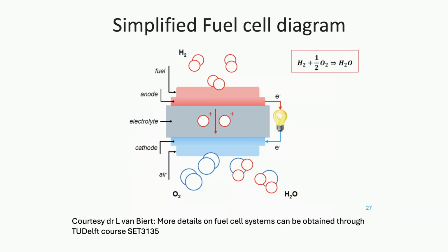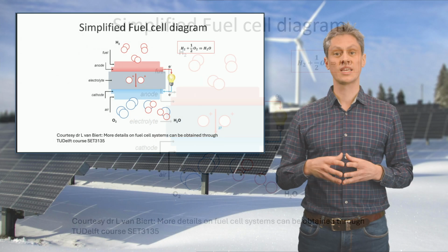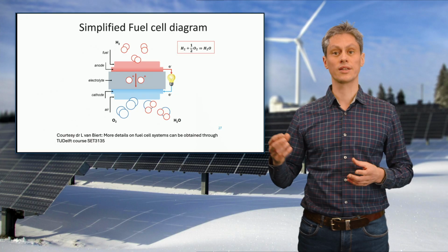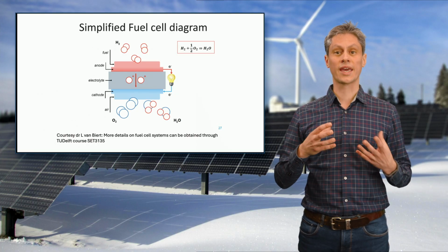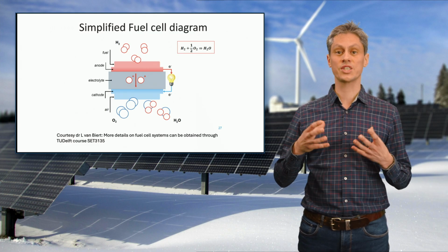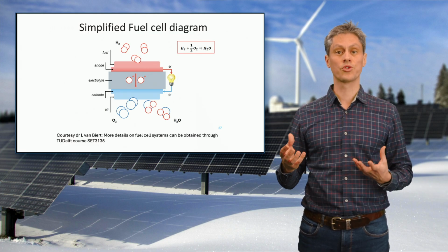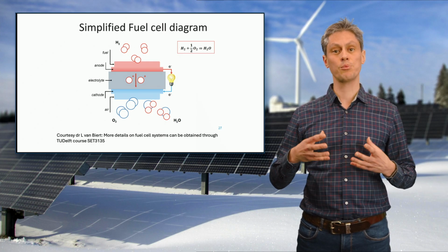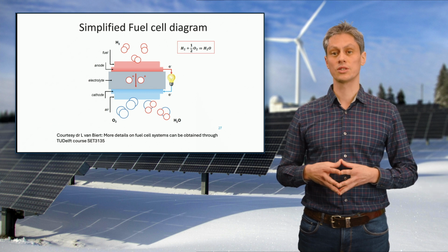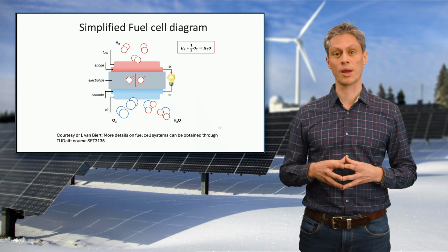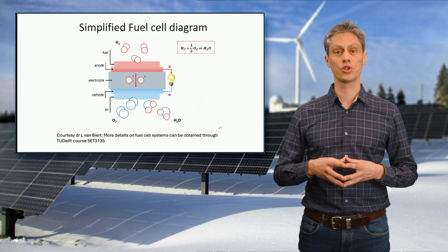In its simplest form, a hydrogen or fuel oxidation half reaction is catalyzed at the anode, due to which 1 electron is transferred into an electrical circuit. To close the circuit, on the cathode side, the electrons are consumed by a chemical reduction half reaction, which enables the transfer of a proton through the electrolyte. The potential difference between both reactions can then be harvested for electrical appliances. The anode, cathode, electrolyte, and current collector often need CRMs because of their catalytic and conductive properties.